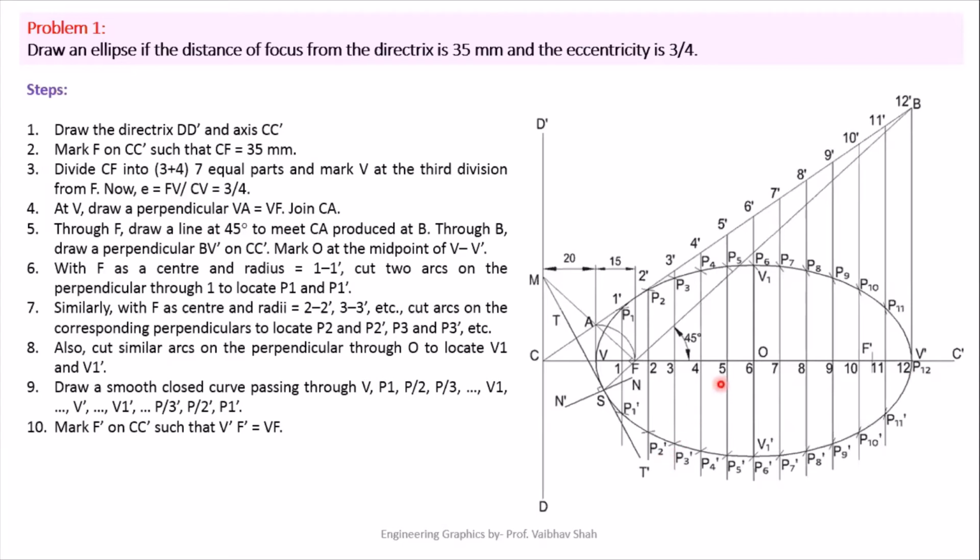And now we'll be plotting another focal point and another directrix on the same diagram. So you have to take the distance of vertex and focal point on your rounder. You'll plot this vertex point in the inside direction, the point which will be your another focus point, which is F dash. And if you take the distance of your vertex point till your directrix and plot it, you will have C dash, and from your C dash you can draw another directrix by the similar distance.